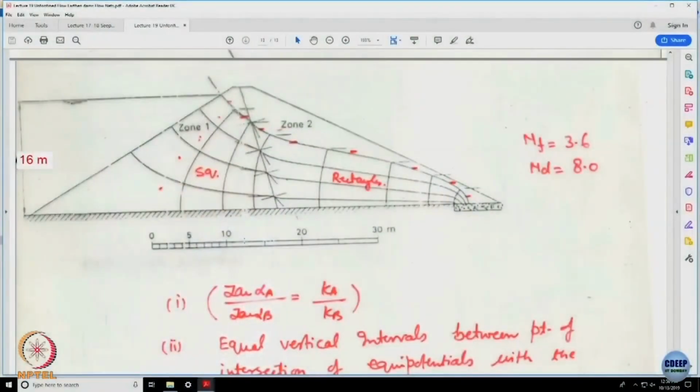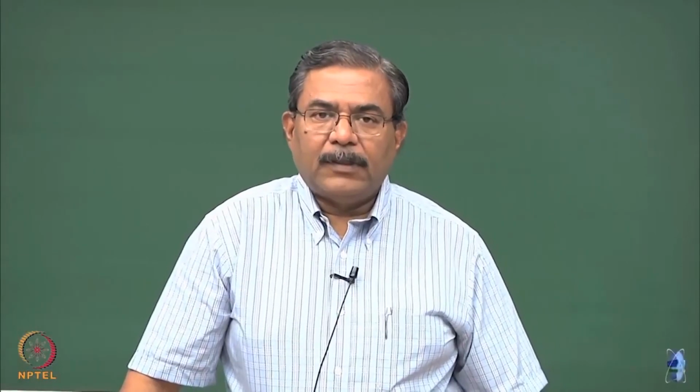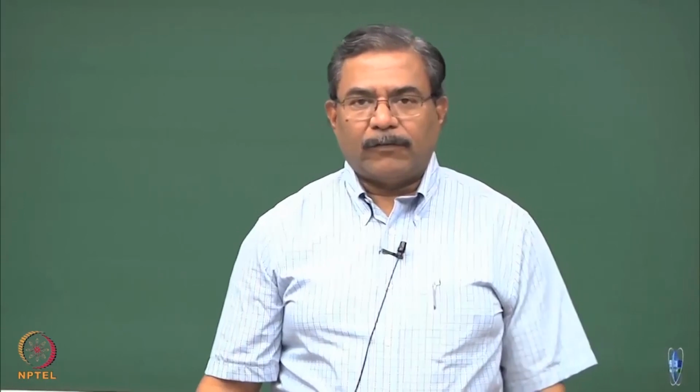In the previous lecture, I had stopped after discussing the case of the sheet piles, and I had emphasized the concepts of determining the discharge through the opening below the sheet pile and the impervious strata. And this is where I had talked about how to compute the number of drops and number of flows which you can utilize to obtain the discharge.